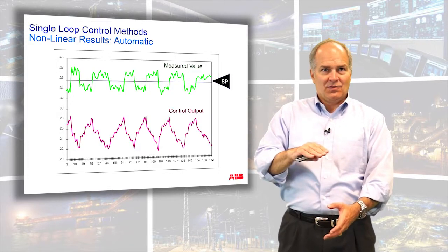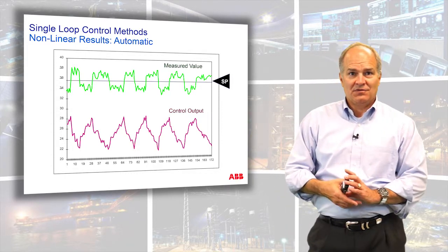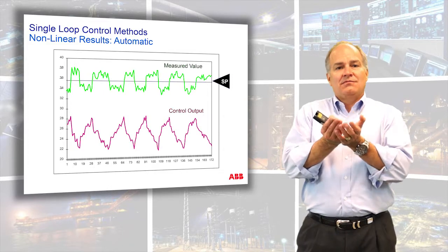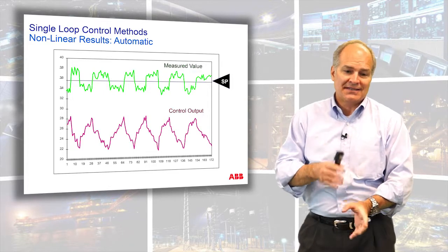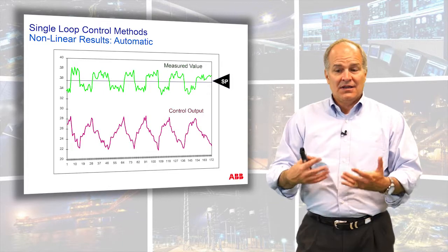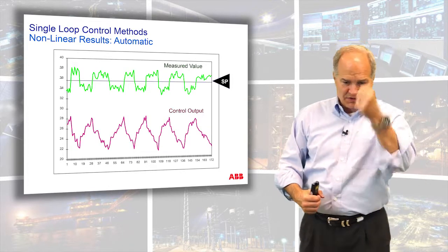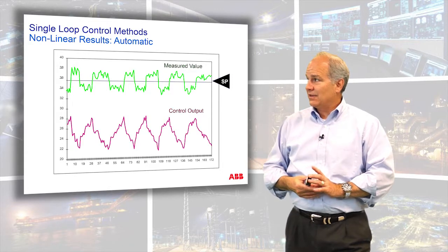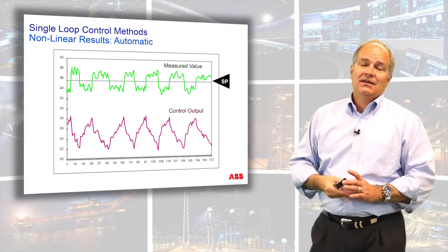Well, then what happens is you get this big rush of process because your actuator just moved. Now your controller's like, oops, I've got an error, so it starts trying to reduce the air pressure to pull that stem back up, but now it's stuck again. They call that static friction or stiction. So stiction gets stuck, and you'll get what's called a limit cycle again because it's cycling. But the classic symptoms are a square wave in the measurement and a triangle wave in the output.